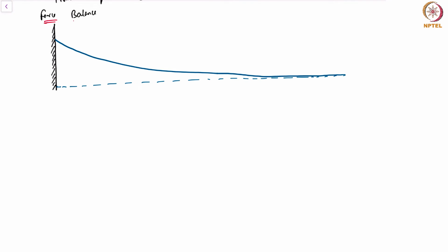That's what we want to do. Now, how do we do a force balance? Let's take a control volume that is enclosing a part of the meniscus, coming all the way from plus infinity to some location x. Okay. So again, it's important to note that the meniscus height at any location is given by z is equal to h of x, where my coordinate system is as follows.